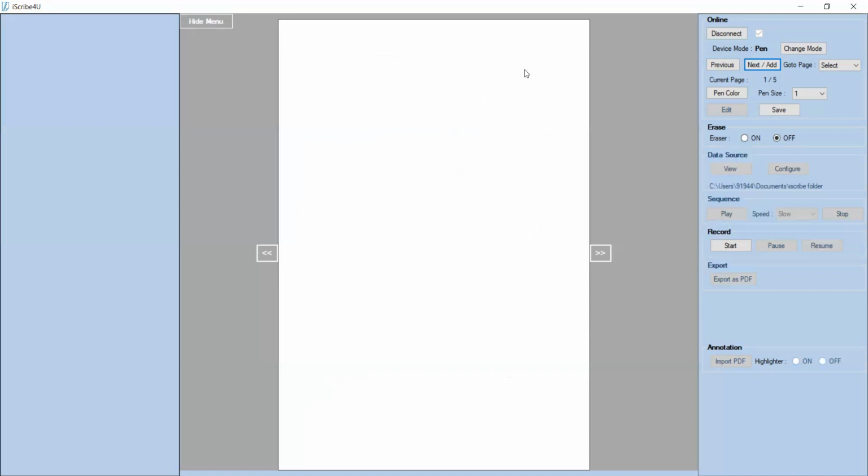Okay, so I'll be substituting in this percentage peak overshoot, which is percent Mp. It is equal to C of Tp minus C of infinity, divided by C of infinity, multiplied by 100, correct? According to the definition, we have this equation.